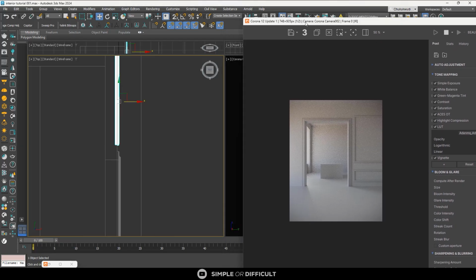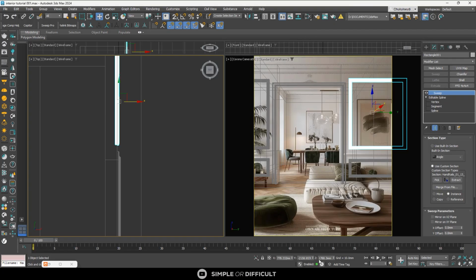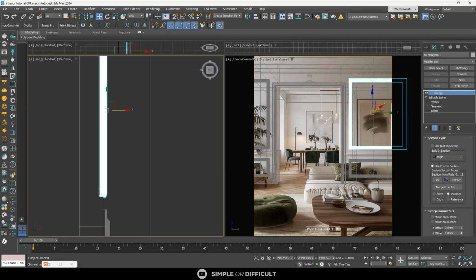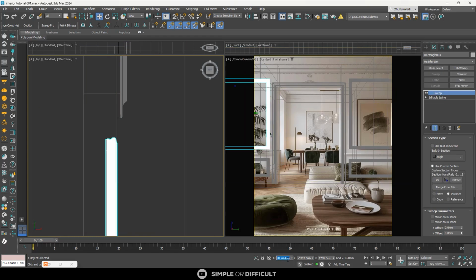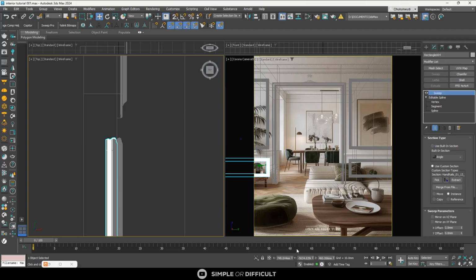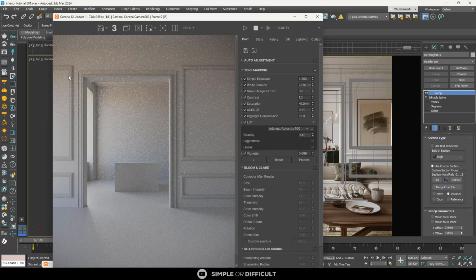So it is selected. Hold on a minute. Let me just shift this into this other screen. You will see I want to move it at the x-axis. This is the x-axis. So I'll just select this and then come over here. Just input this figure inside there and that will take it where it needs to be. The same thing over here as well. Hit enter. And then when I bring this out again, you're going to see we have the wall paneling that we want.